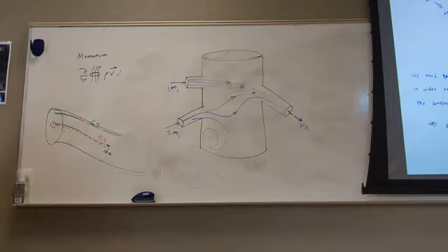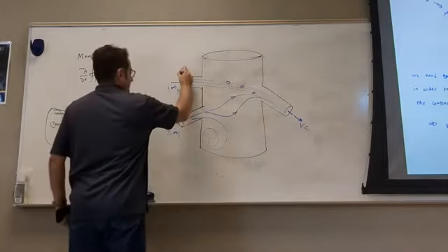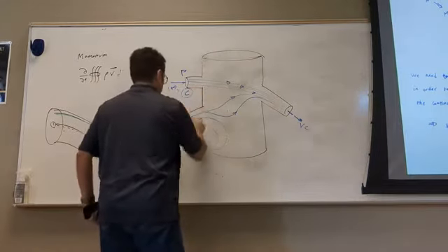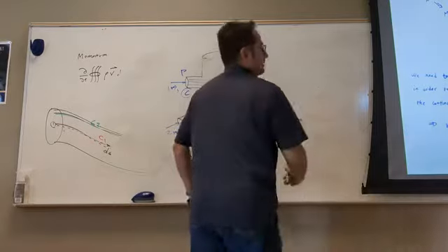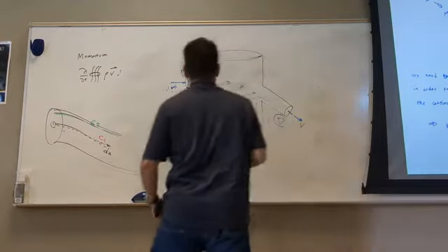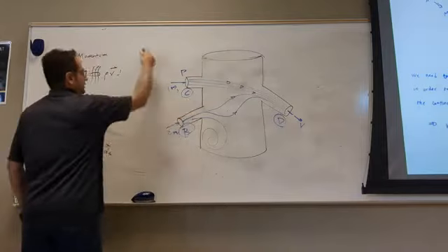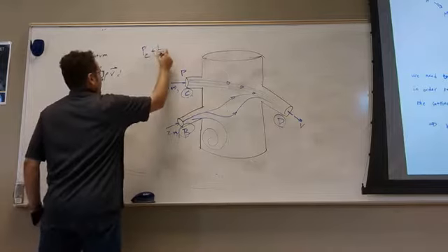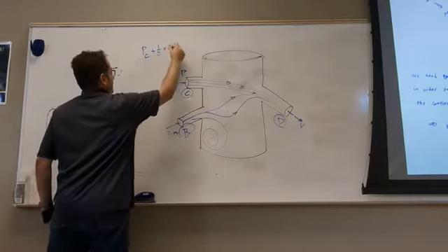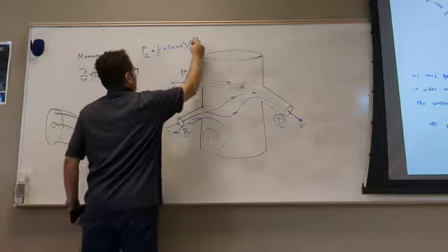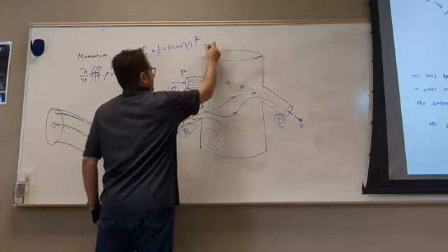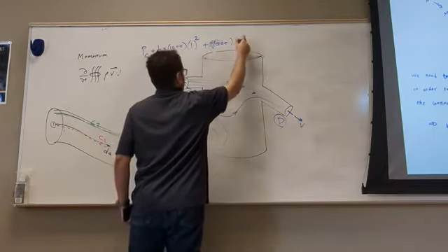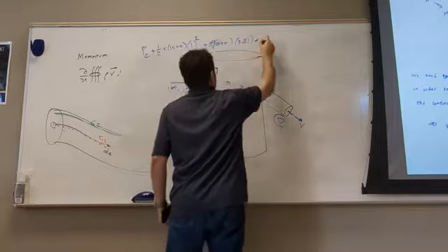All right. So you have pressure here called P. This is B, C, and D. This is not C, this is D. Right? So you have pressure here. You want to find pressure here, so taking C, PC plus 1/2 of rho, which is 1000, times velocity here squared, plus rho, which is 1000, times 9.81 g, times Z.